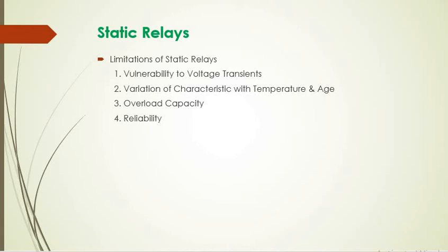Now, electromechanical relays have high reliability due to the fact that they have a smaller number of components and that each component possesses good reliability due to long experience gained in manufacturing practices. Static relays were less reliable initially for a few years, until the discrete components proved their reliability. Careful choice and quality control play a vital role in reliability of static relays.